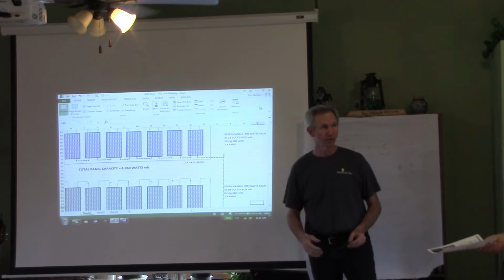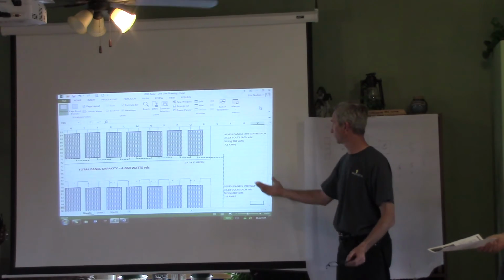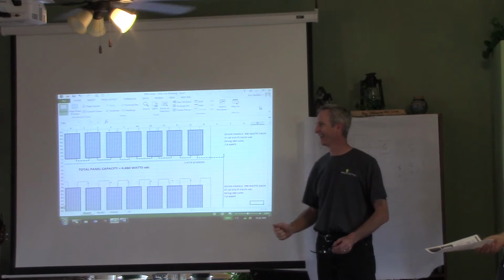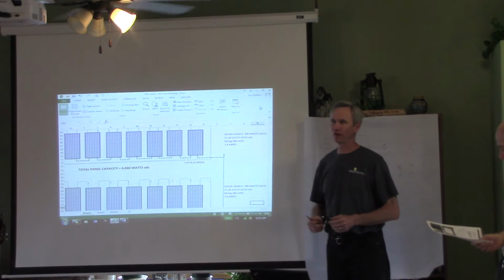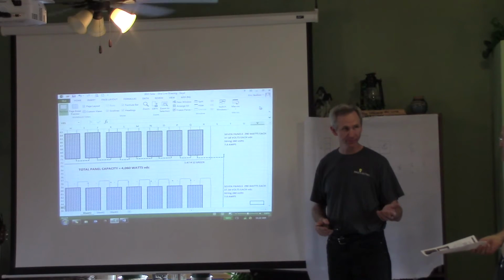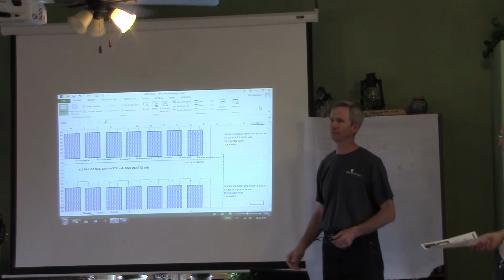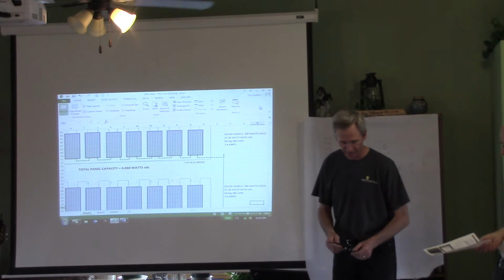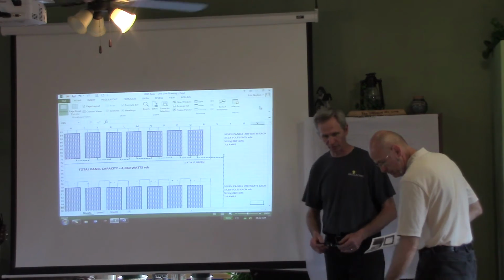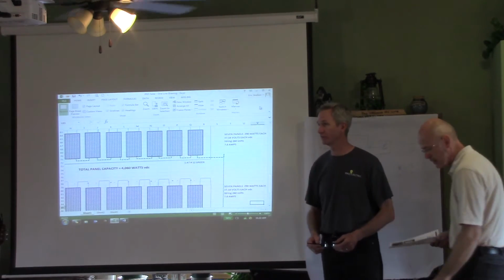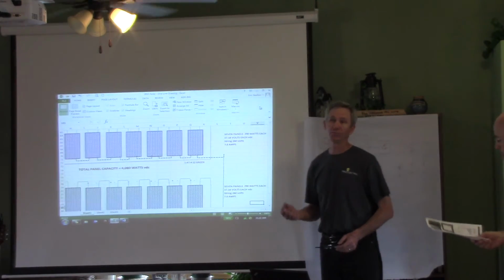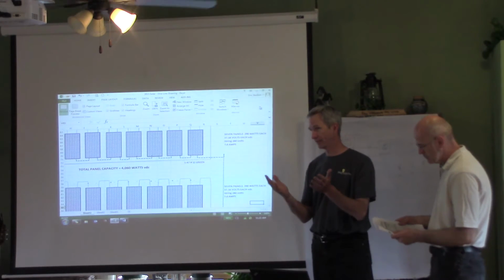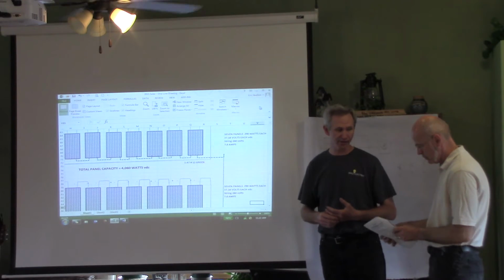That's our range. We couldn't put 2 panels in, because that's only about 70 volts. That won't kick it on. So we had to get in that sweet spot. 14 is too much, as we just figured out, all in one series. So he says, wait a minute, what if we do half? What's 7 times 37? About 259, or 260. But that means we take 2 strings and put them in the inverter. Will the inverter handle it? Yeah. We're above 230.